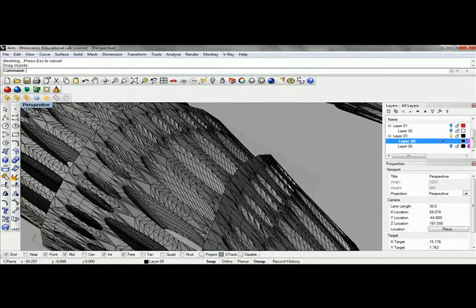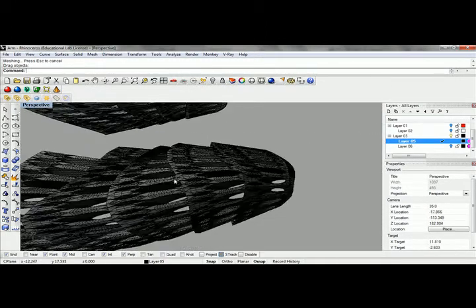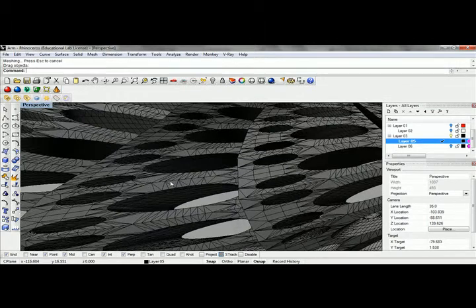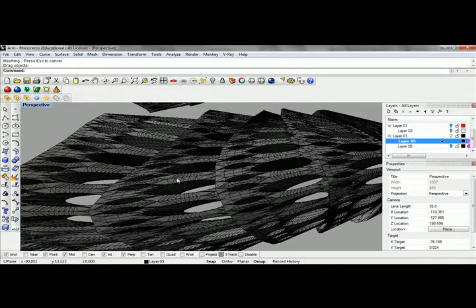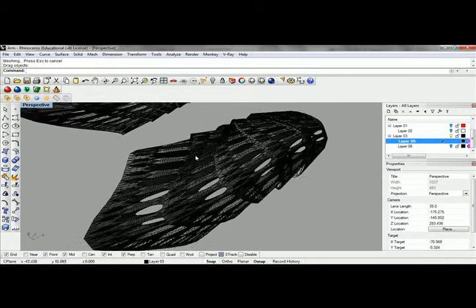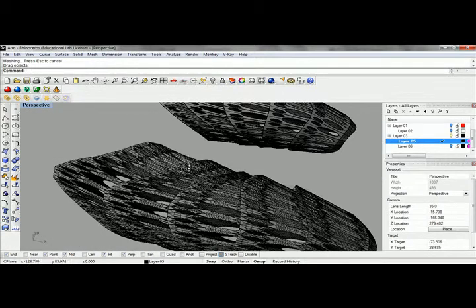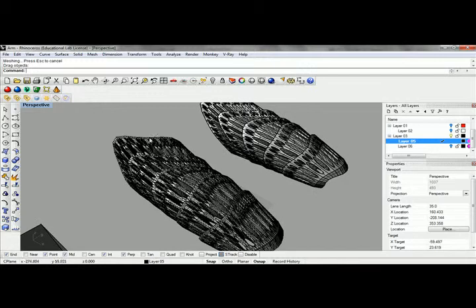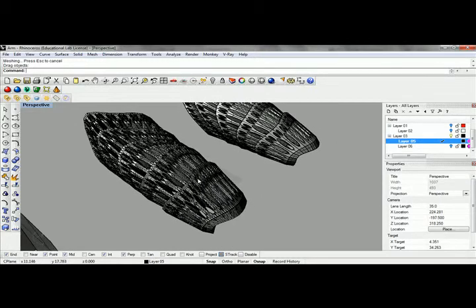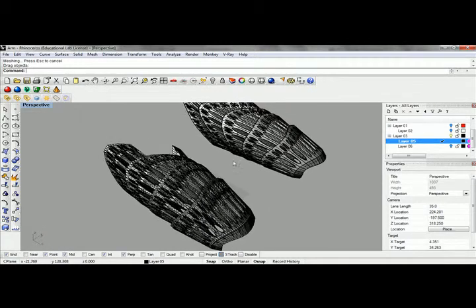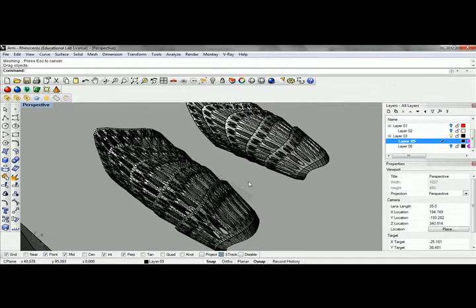And you'll see that Rhino does a pretty nasty job of actually breaking this up, and doesn't really make this into a nice series of geometries that can be easily utilized. Rhino is not a mesh modeler either, so there's not much you can do with this once you get into it. And so really, if you end up tearing holes or something at the mesh command, which does occasionally happen, you're going to want to go back into your geometry and change your mesh generation settings and things like that, or remodel some of your geometry.